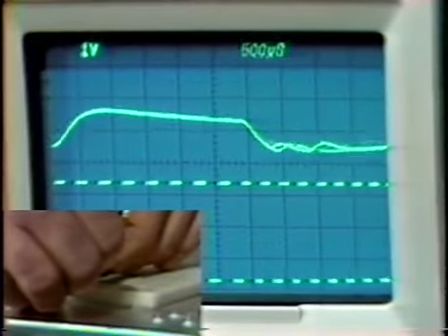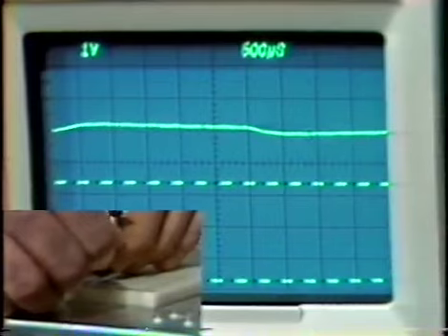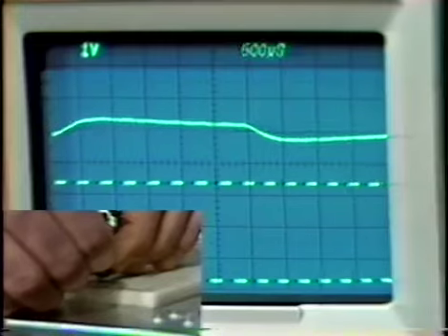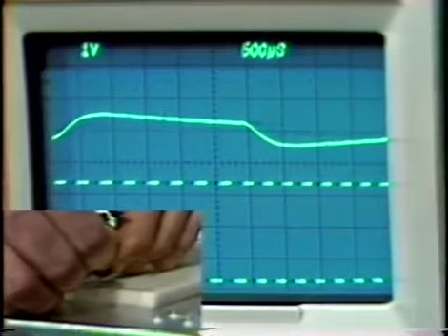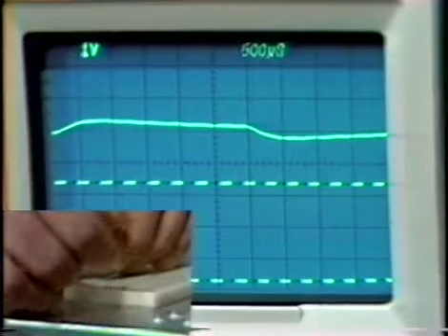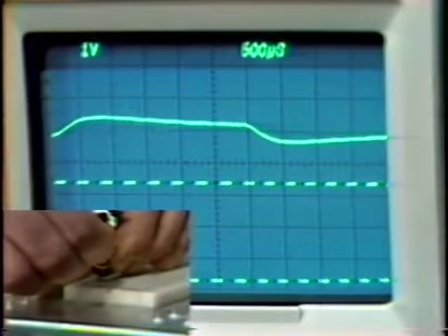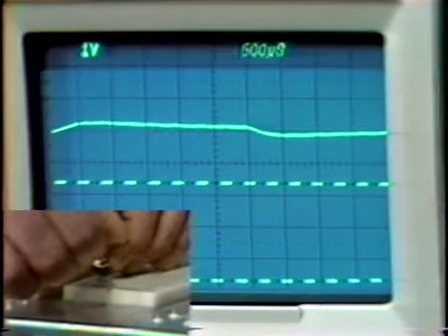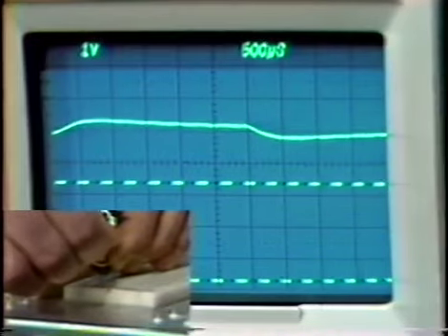We can again get into nonlinear behavior quite easily, but if we don't go to that point, we can see the FMing behavior on the first part of the signal. If we were direct coupled into the VCO, we'd see that the first half maintains its DC level, and the frequency on the first part of the cycle does not change as we change the amplitude. However, the frequency in the following part of the trace we notice changing, going toward higher frequencies as we increase the amplitude of the signal applied.